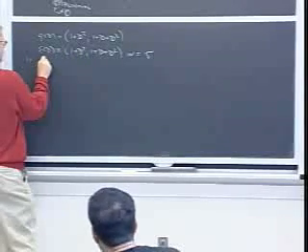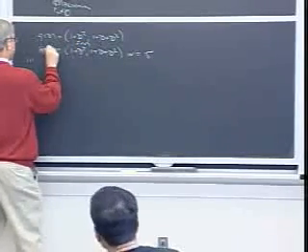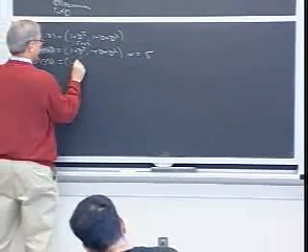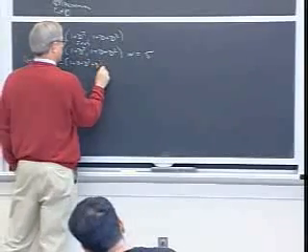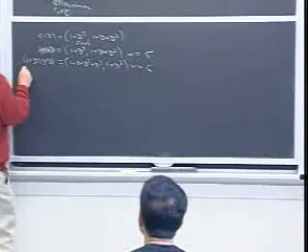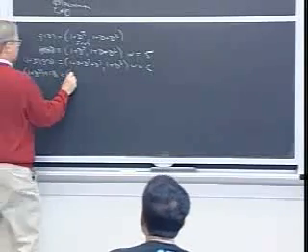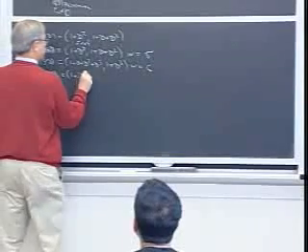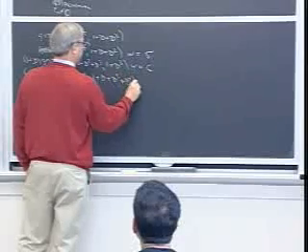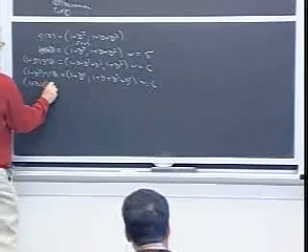So this is going to be a table. We have g of D, 1 plus D times g of D, which is equal to 1 plus D squared plus D cubed, 1 plus D cubed. That has weight equal to 6. What's my next longer one? 1 plus D squared times g of D equals 1 plus D fourth, 1 plus D third plus D fourth. That has weight 6. 1 plus D squared times g of D.